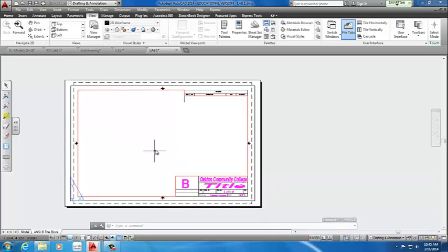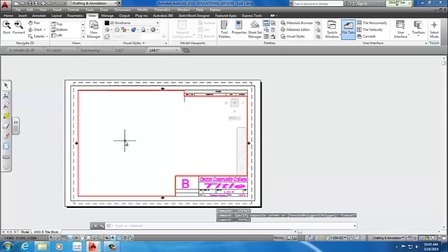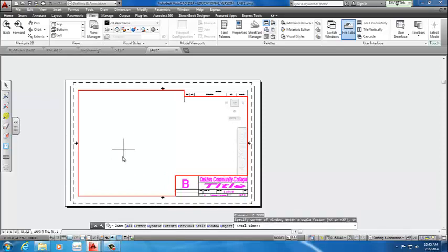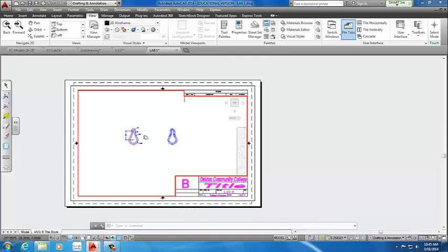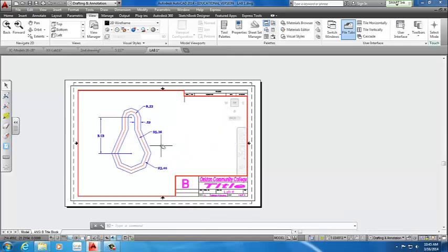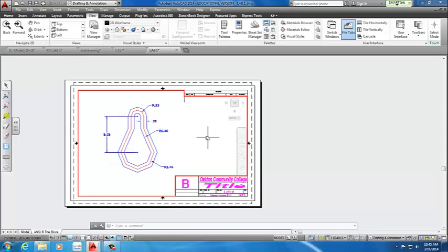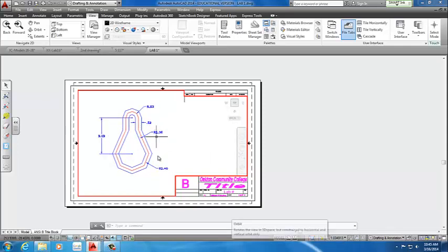That happens a lot. So we're going to double click inside our viewport. And we can type in zoom, Z, enter, A, enter for all, or extents. Both should work. It brings out the drawing. Move it in the corner so that you will see only the 2D drawing. We don't want to see the 3D drawing yet because we want to see the 3D in an isometric view. And if you want this to be to scale, so that if somebody had a ruler and had it printed out, they could actually measure it out.